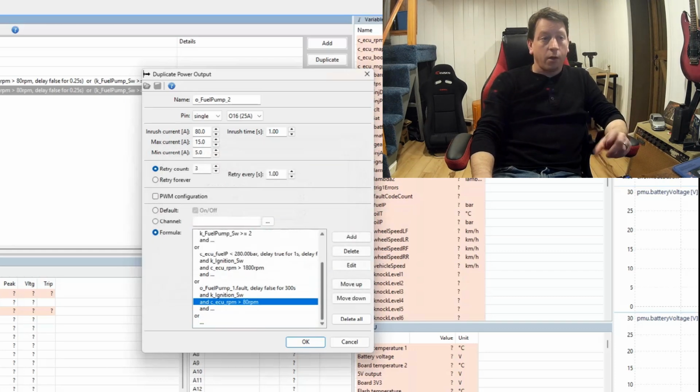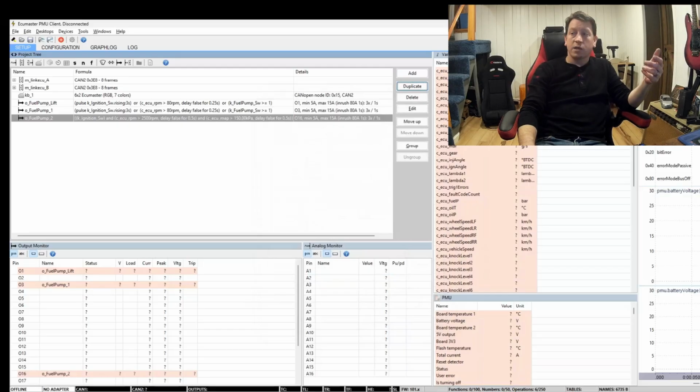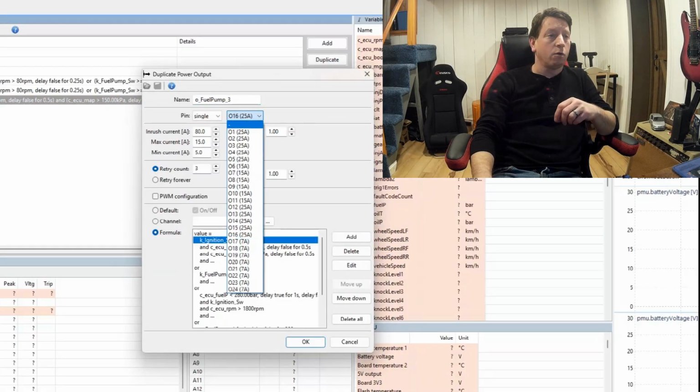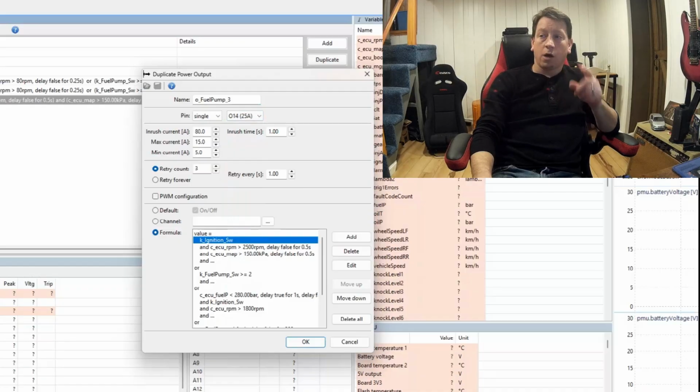So now we've got a couple extra little layers here of this pump. Now it's great, right? I've got 2 pumps, and my second pump will turn on if my first pump fails. But what if I need 2 pumps to run this car? Now I've got my second pump running, but I'm not going to have enough fuel pump. That's where having this third spare pump comes into play. A lot of people might wonder why you have a dead pump in there you're never going to need. You'd have to wire to it, and yeah, it saves you from installing it, but that's not that useful. This is where this really comes in handy. I don't have to go in and change anything. You can have a fuel pump die and have the ECU automatically switch to your third pump. I've had this happen. Driver swears the pump didn't die. It did. This kept him on track.